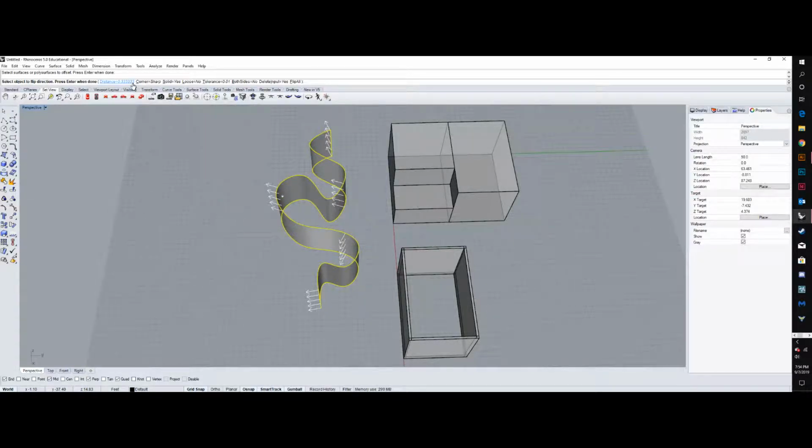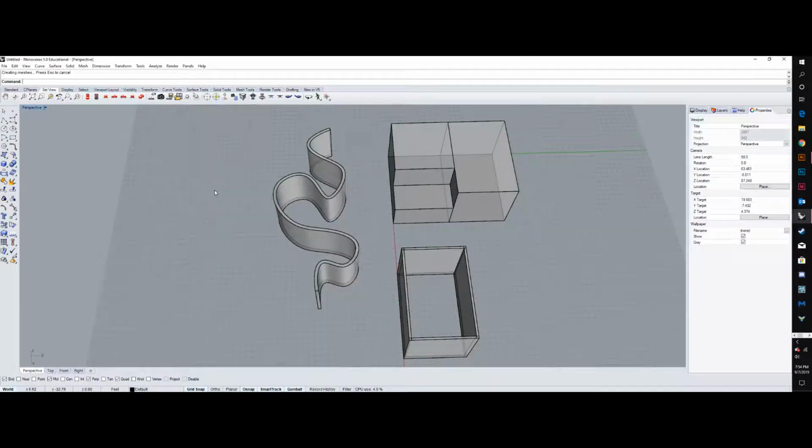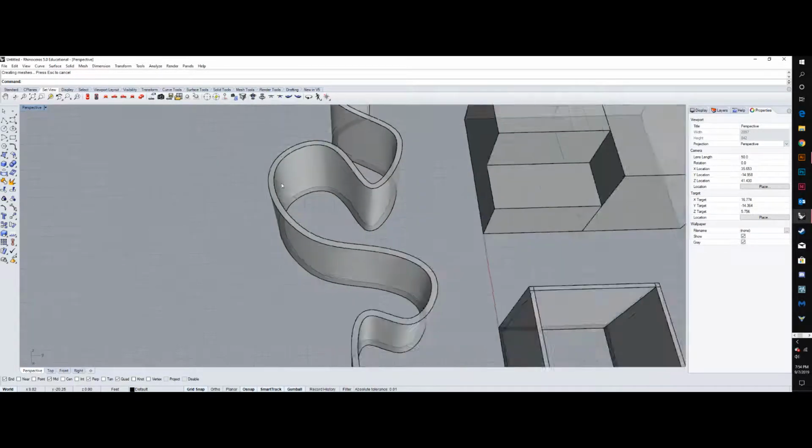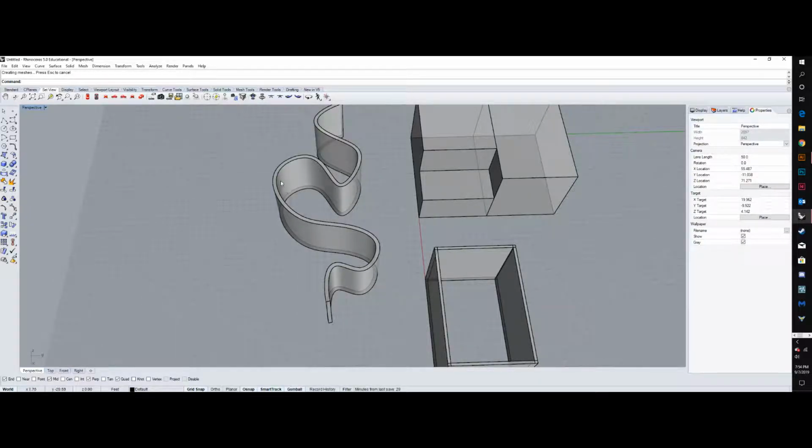Let's say we want this to be 1 foot wide. I'm going to change the distance to 6 inches and only offset half of that foot to the left, and then I'll do it again to the right. So we've changed our distance to 6 inches or 0.5 feet, hit enter. So that's a 6-inch wall now, but we want it to be a 1 foot wall.